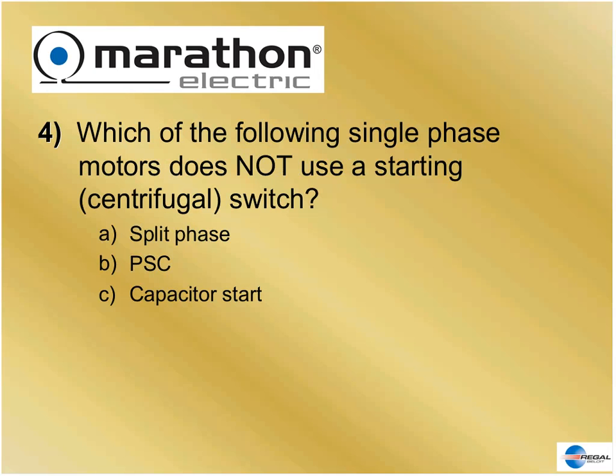Which of the following single-phase motors does not use a starting switch? That's this switch right here. We take the start winding out of the circuit with this switch, remember. Which motor does not have a start winding that comes out of the circuit? If you said B, PSC, final answer, you would be right.